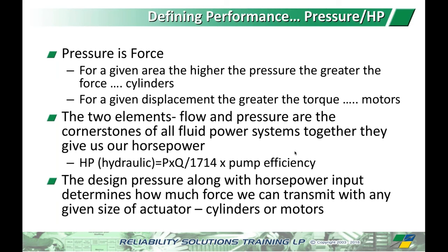Rule number two, pressure is force. So the greater the pressure, the greater the force. So if I have a bigger load, then I'm going to need more pressure to overcome that load, okay? And of course, pressure is also related to torque if we're talking about rotary actuators. Now, we combine the two elements of flow and pressure together, and they give us horsepower. That's power. And there's actually calculations you can do based on flow and pressure that will calculate how much work you're actually doing, okay?